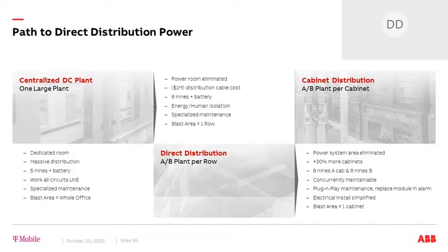Our power density increased so much that we couldn't fit the primary distribution cables. I could either move 30 offices to new locations or I could find a solution. We moved the batteries to the end of each row. This eliminated massive amounts of cable and saved more than enough money to pay for our distributed power plants. Dual system failures were now limited to a single row.